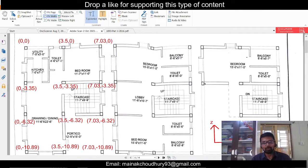As you know, all the buildings higher than zone 2 have to be compulsorily designed by response spectrum analysis as per the IS code. So this is a very important method, so let's go ahead. This is the building which is already designed by some other contractor. We'll check whether this design is okay or not after completing the design, and also we'll see the steps of the response spectrum analysis.